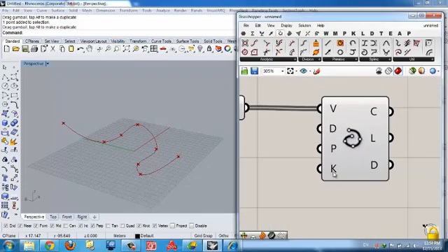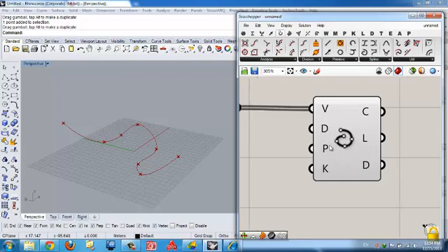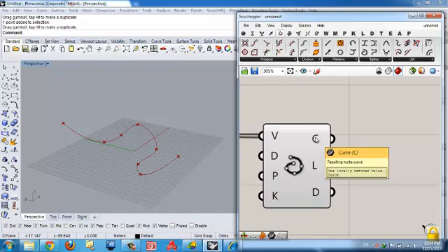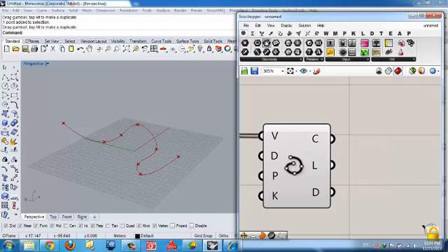We have 3 inputs here, but it just ran, you know, the interpolate thing just worked. What you need here is a degree or a curve degree, periodic, is it closed or open, and knot spacing. Okay, I just dismiss here and go to the next part. We have a curve here. So the sign when you see this hexagon with the spiral thing in the middle means that it's a curve, and you can see it here, right?